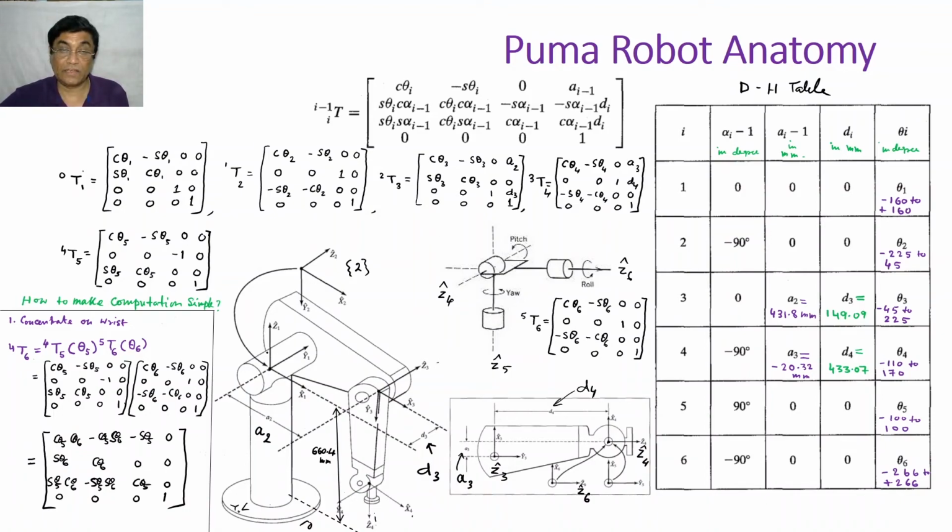first you attach coordinate frame because you identified the motion. Okay, once you identify the motion correctly, you need to assign coordinate frame, and here you need judiciously to do that. Okay, so that as far as possible, initial parameters should go away, and so that your computation will be simpler. So that's why we did. Okay, 0 and 1 is attached here, 0, 1 and 2 actually attached here.